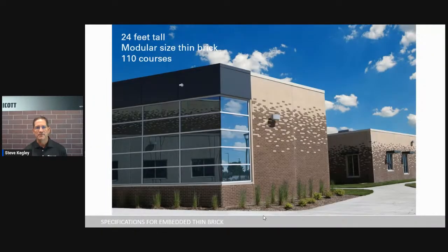Same thing with flats. And I've had a lot of architects. We do an AIA continuing education course in support of precast. Endicott does, and we've given this thing between the five of us probably 100 times. And we explain to architects these tolerances about warpage and bowing and lengths and things like that. We try to explain to them, you need to work with the precaster and make sure they're telling you what they would like to have in terms of a dimension. So what if it moves 2 inches or 1 inch from standard, 24 feet or whatever? That's okay. If it works better for you as a precaster, we think that's the way to go.